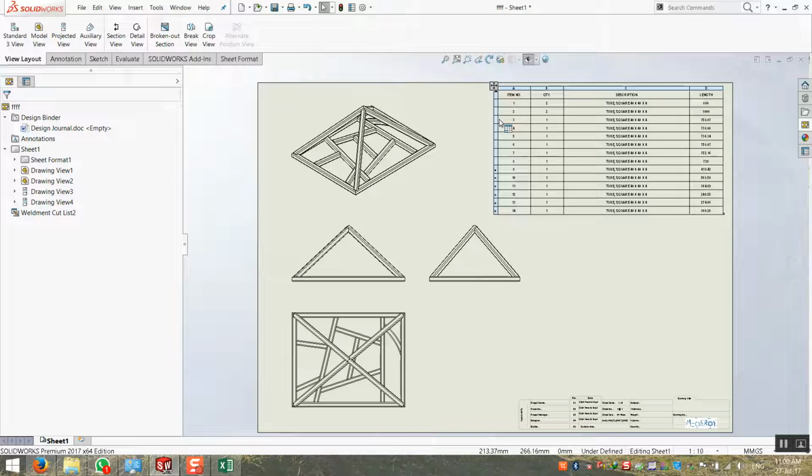You need to add something for the flat view. Flat view or top view with the hole. You will need to add a top view for him. You will imagine that you will see from the top and draw for him another view from the top, okay, with this dimension also 80 because it will be the same, and the 100, and have this circle.